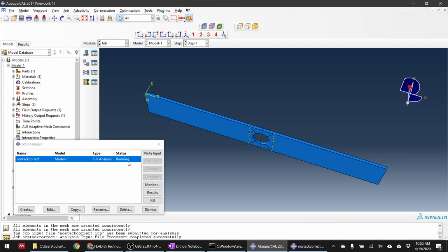The stacking direction, right? So in this video, in addition to showing you how to model the composite, to input the parameters for composite, and how to make different fiber orientations in a continuum shell, I also want to emphasize that when you're using continuum shell, or if you want to use cohesive elements, you need to set the proper stacking direction, so that ABAQUS knows which one is the top surface and which one is the bottom surface, and can do proper calculations.